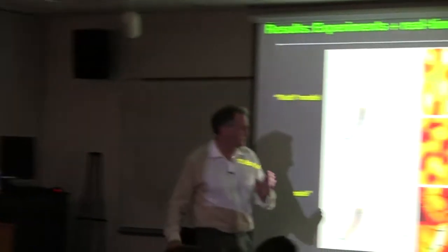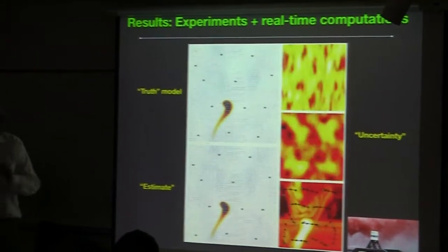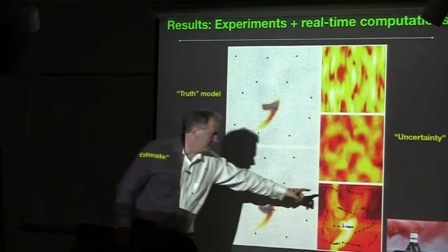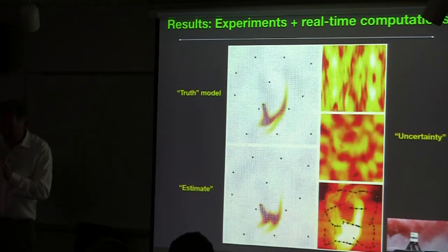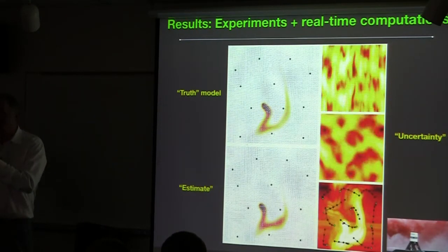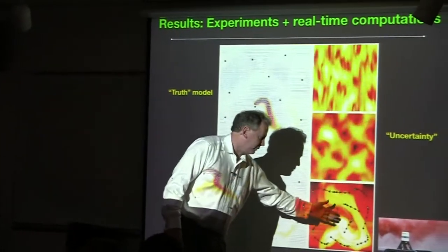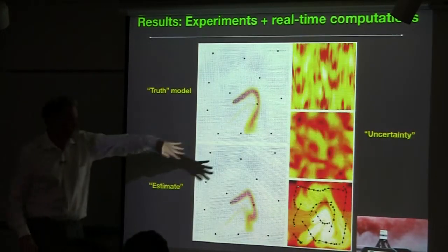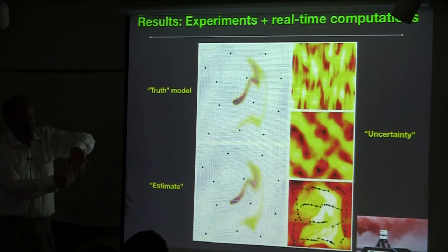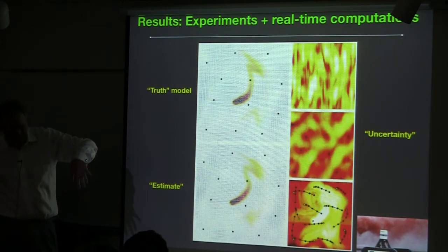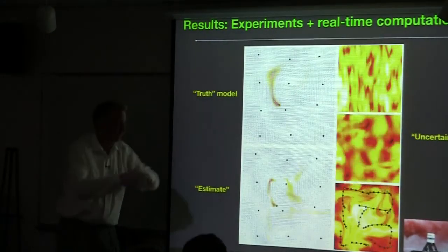So this is called a receding horizon model predictive control framework. We develop a trajectory for each of the vehicles, and then each of the vehicles goes to, say, the first of 5 waypoints on each of those trajectories, and by the time it gets to the first waypoint, we've updated the trajectory a little bit, and we send an updated set of trajectories. If our comlink breaks down for a while, we actually send it several waypoints on the upcoming trajectory. It goes to the first, and if it hasn't received new information from the supercomputer that it's in radio contact with, then it will go to the second or the third until it gets its updated set of trajectories, and it will go to those.